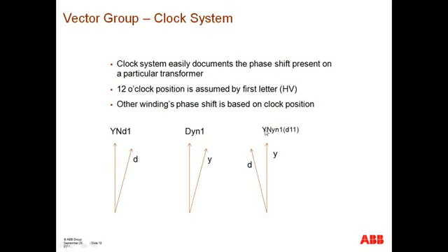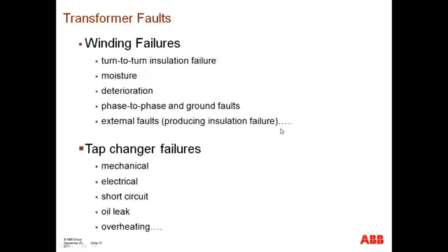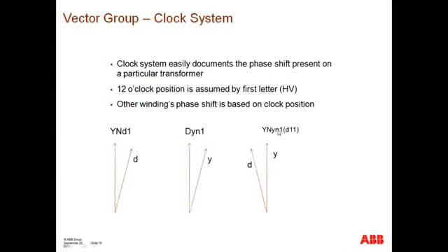again high voltage is a Y winding in the 12 o'clock position. Low voltage is a Y winding, okay? So YY is essentially in phase. And this is actually a mistake on this particular slide. It should be YN, YN, not YN, YN1.